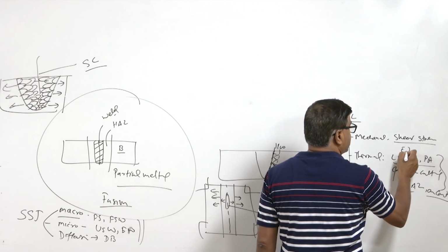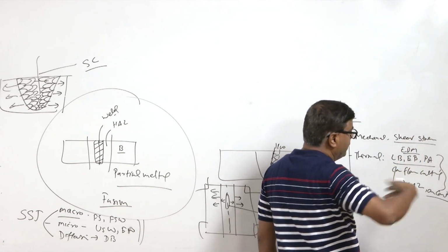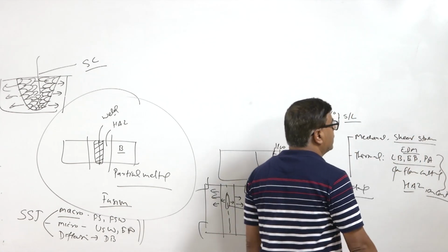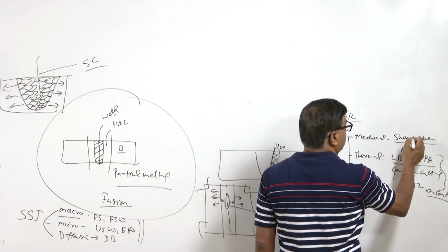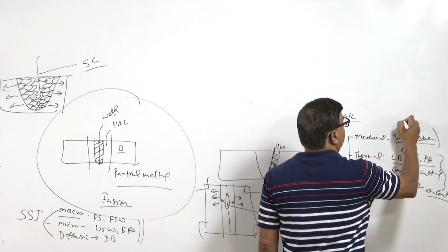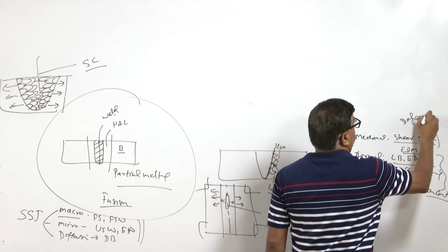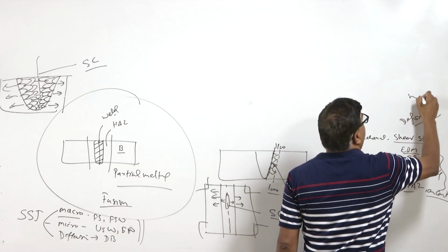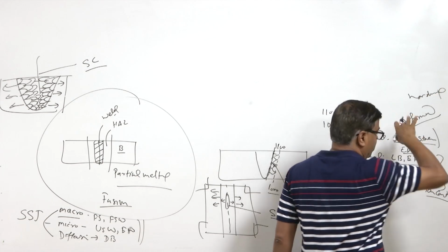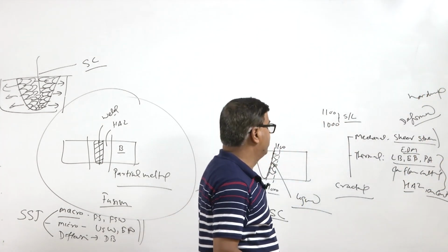Similarly, there is electric discharge machining also, where thermal energy is used for removing the material in a very controlled way. In mechanical, near surface layers will have the deformed layer, which results in the hardening of the surface and improves the strength and the fatigue performance.